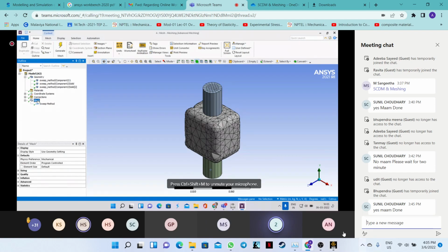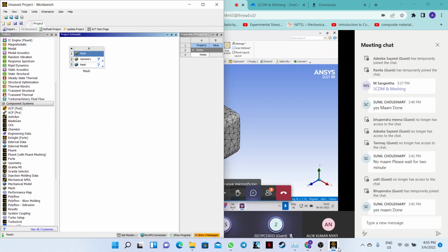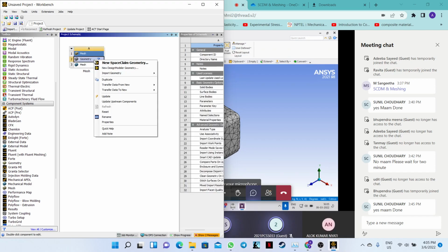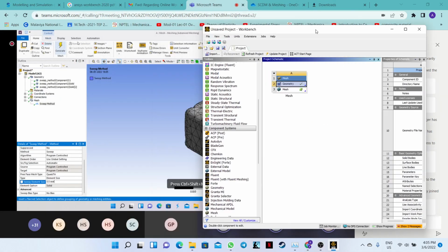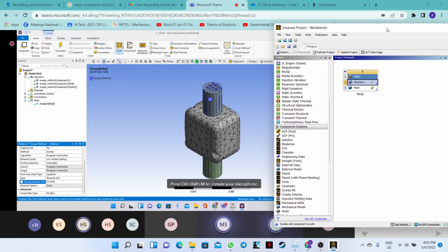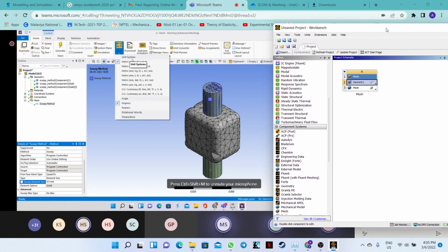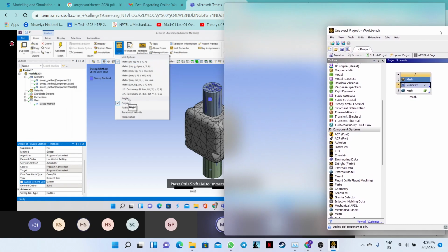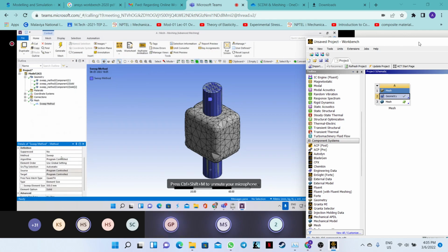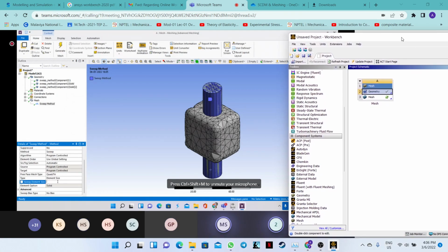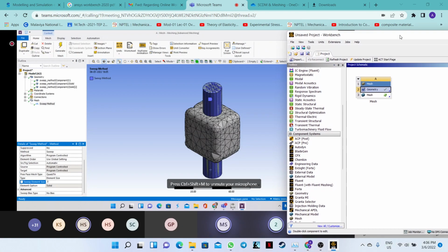Go back to the details. You have selected 0.5 meter of element size. What exactly has to be done? You need to change your units first. In the home section itself, you have units, right? Towards your right, units, and change it to the third one, kg Newton, or you can put a conversion value there. Now you specify 0.5 and press enter.